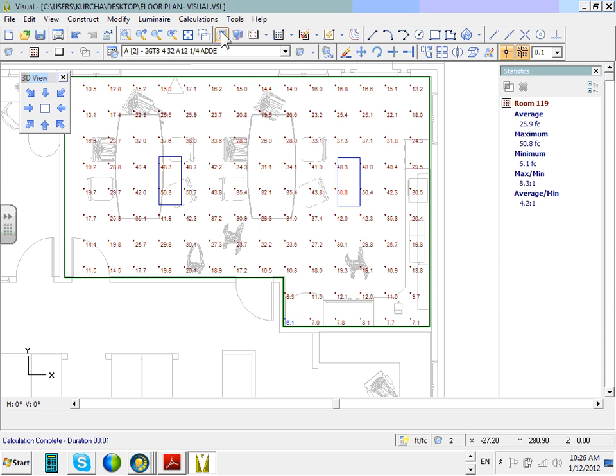When you build the model, this is where mistake number one happens, when you build the box. If you don't put the right height, you have to delete the model. They don't allow you, I don't know why, to edit the height of the box. Unfortunately, you can edit the name, but the height you can't edit. So say the height of this room was wrong.